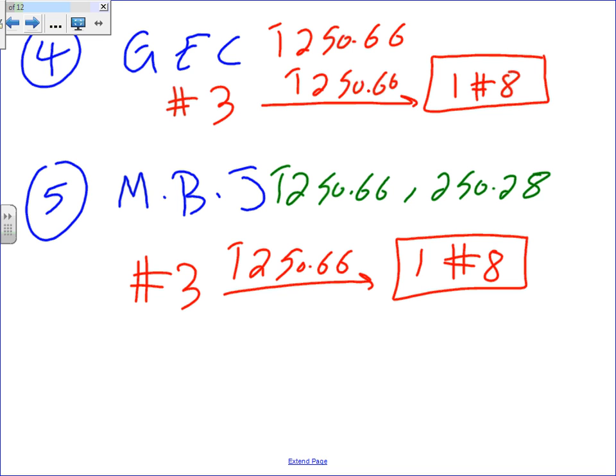Okay, the challenge with number 6, guys: if your grounding electrode conductor is smaller than number 6, you have to provide physical protection. You have to put it in a conduit. So, moving forward, you met the code. Engineering-wise, practical-wise, I wouldn't go for less than number 6.